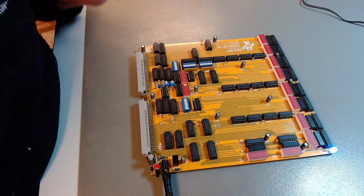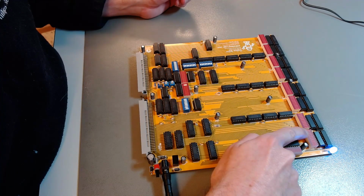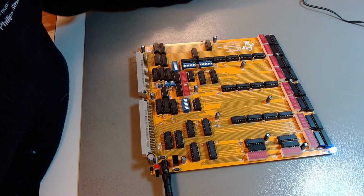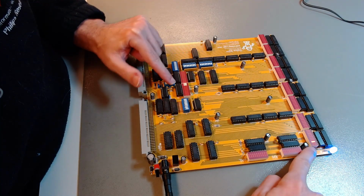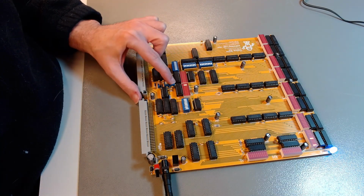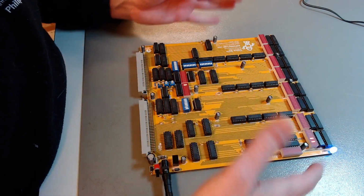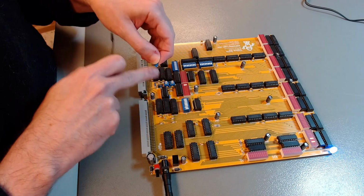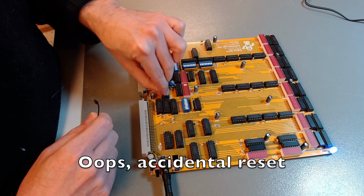Let's do a few tests. The first thing we can do, the program counter is here. Let's see if it will count before we set any control bit whatsoever, because it should always count. So if I press clock, it counts, you see? So that's working as it should. It is counting. So now, it's in standalone mode. It will be only in system mode if I place this shunt on this pin header here, but right now it's in standalone mode.